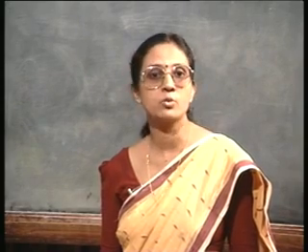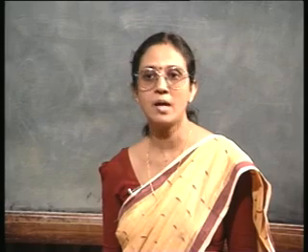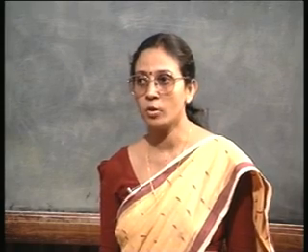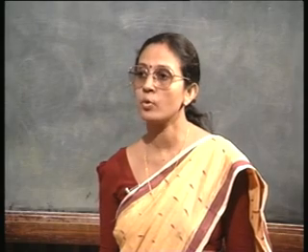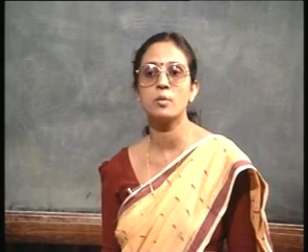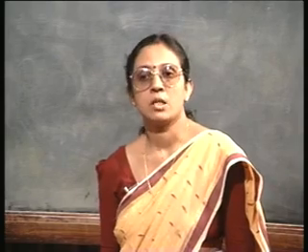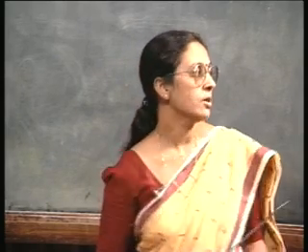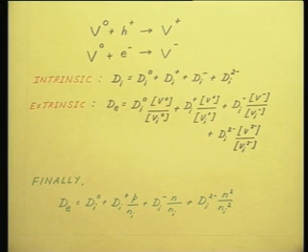So, in a real life situation everything is possible. You can have for very high concentration d proportional to n square, for moderately high concentration d proportional to the concentration either n or p depending on whether it is donor type or acceptor type, and you can also have d is a constant, in which case we say that the intrinsic condition is dominating.